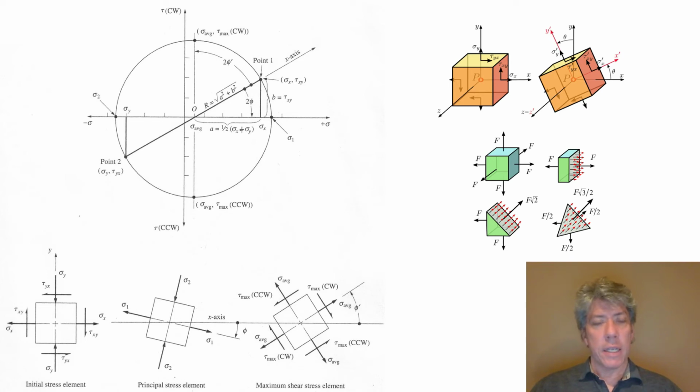As a matter of fact, it is the case that you can find orientations where the shear stress goes to zero. You can also find other orientations where the shear stress would be maximized, because again, the material doesn't know about shear and normal stress. To it, it's just stress, and it's in a direction coming off the face that is not necessarily normal or just along the face itself, right? We choose a different orientation, and that's going to change the magnitude. All we're really doing is decomposing vectors here, right? There's a vector sum of tau xy and sigma x. If we change the direction, we need a different magnitude of that vector, and by the way, we have to redecompose it.